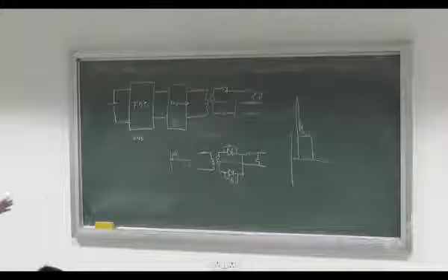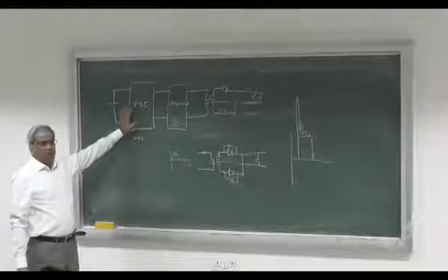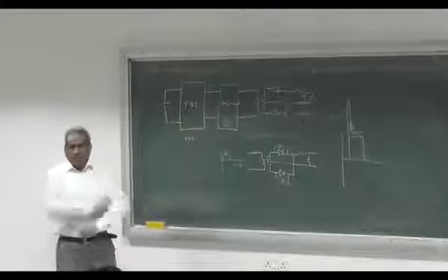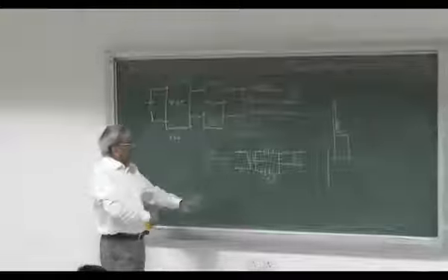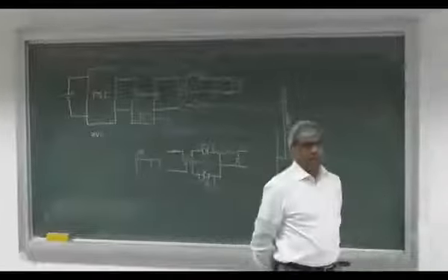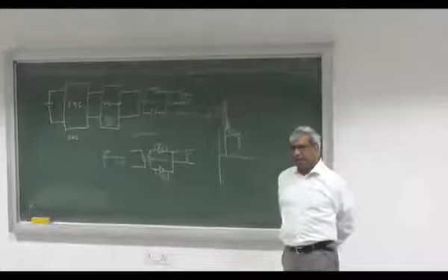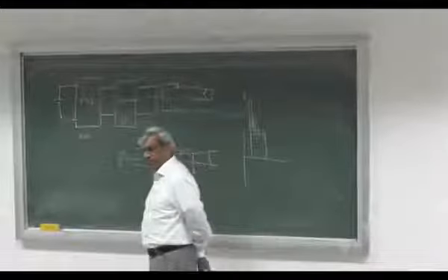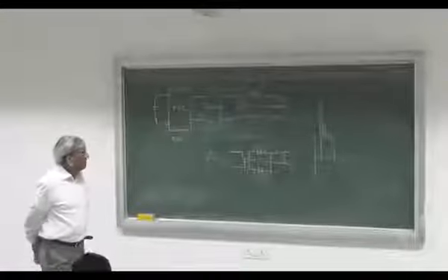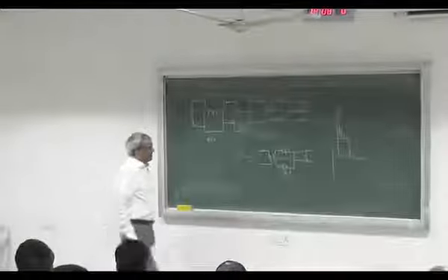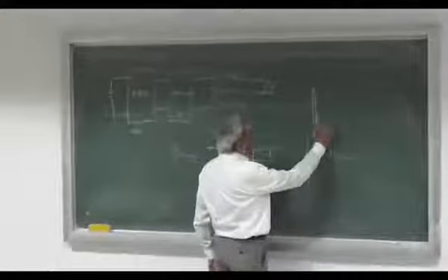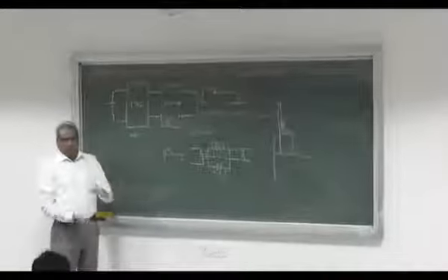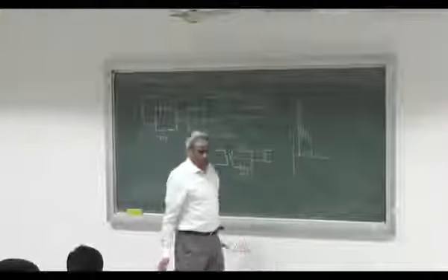So we have solved the problem on the inverter side, but we have not solved the problem on the rectification side. At the rectification side, we have this high peak voltage at the time of turn off. And also, this steady state value, which is Vi, keeps changing depending on the input voltage. So the voltage stress across the diode is not controlled.